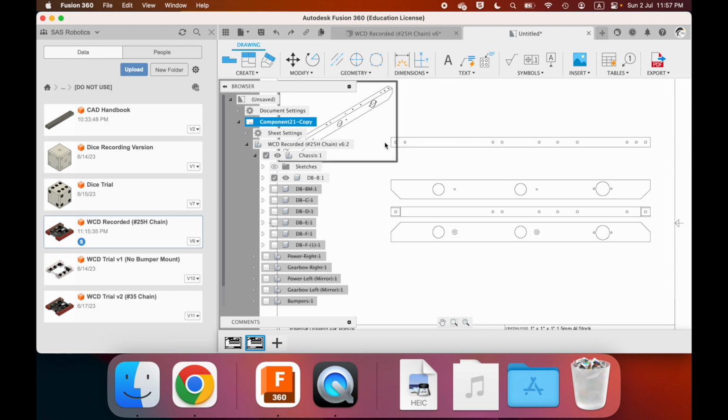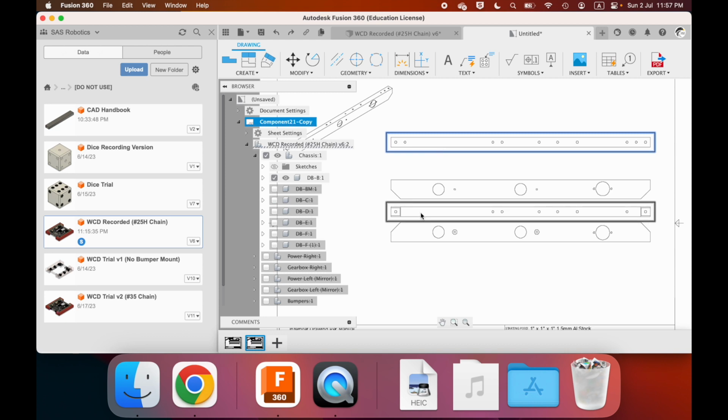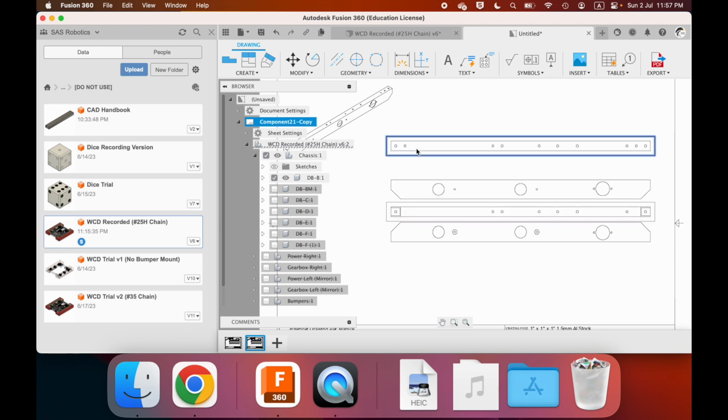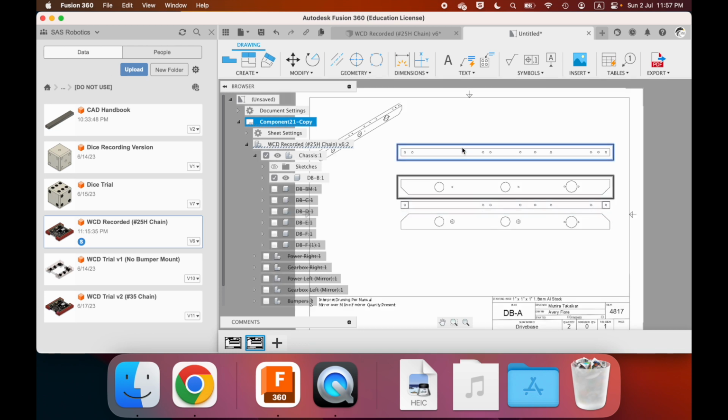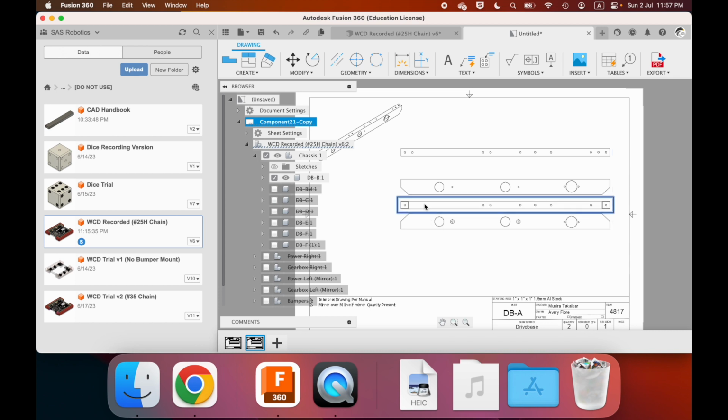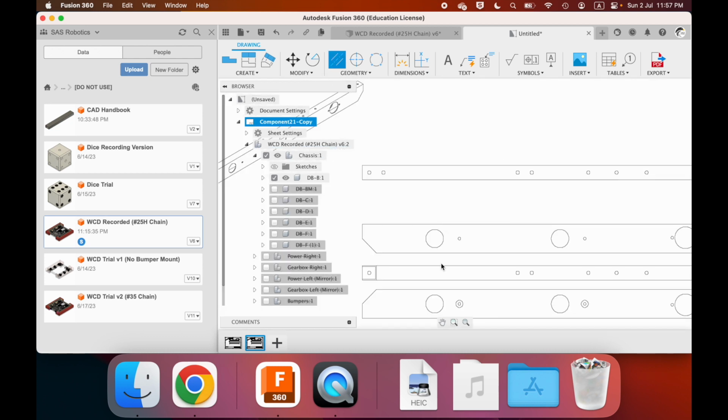The mirror line is going to be either a line down the center of this side or this side, because this side is going to have a bunch of markings on it. We're going to put the mirror line on this face. Okay, so what I can do is click center line, click that line, this line. Center line is drawn. I'm going to extend it out a bit.